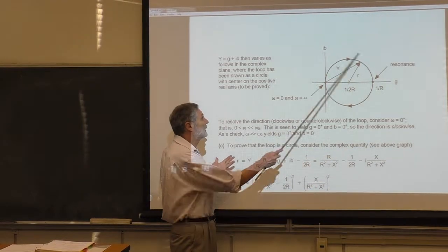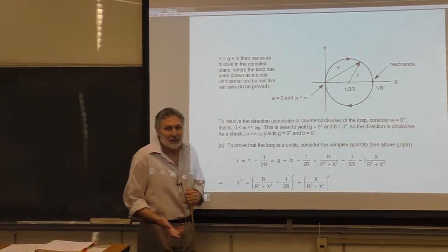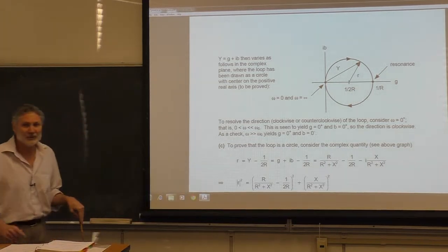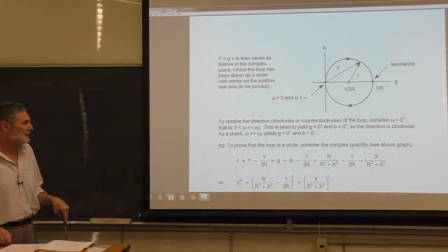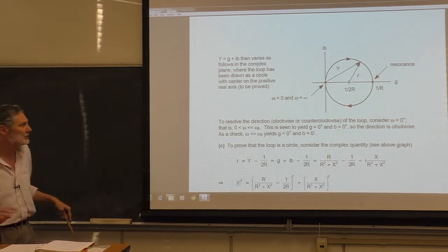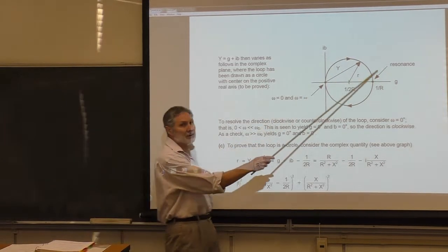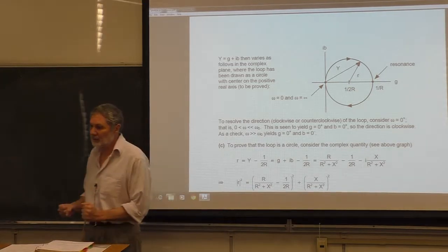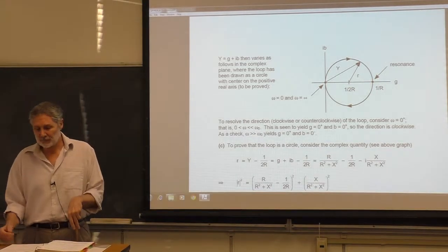And you plot this, and you just measure the diameter and take 1/2 that. From the diameter, you can get the mechanical resistance. So that's one of the uses. That's why this is important here. You can determine that parameter for an actual transducer.